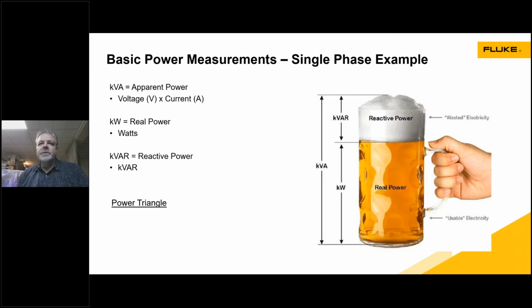We talked about watts, which is the real power portion, but let's talk about the different factors involved with being able to get us our measurements that we're looking for. Right out of the gate, apparent power is also known as system capacity. What is the ability of the utility to provide us both voltage and current? It is strictly a multiplication of the two, voltage and current. This is what the utility may be having to provide, voltage and current, but in our case, we're looking at watts.